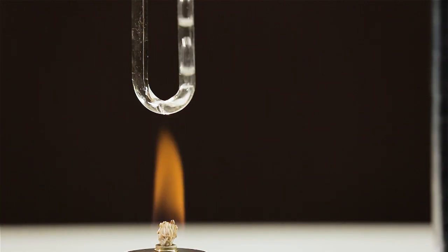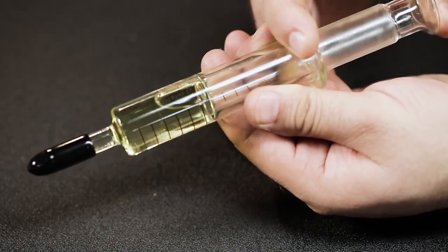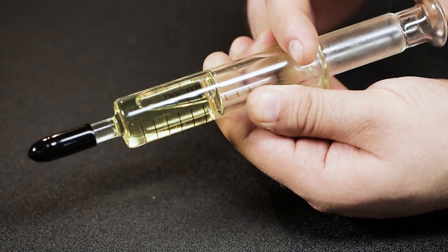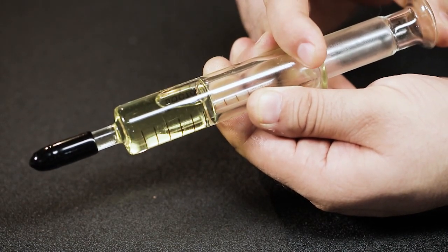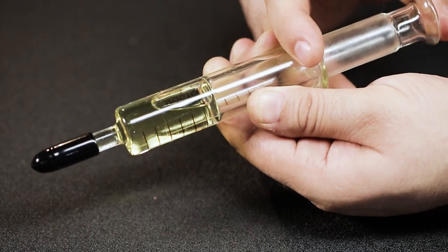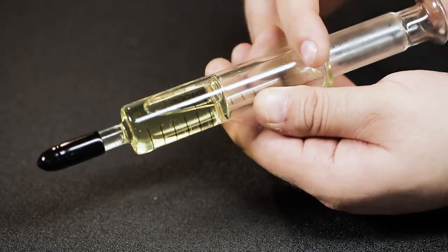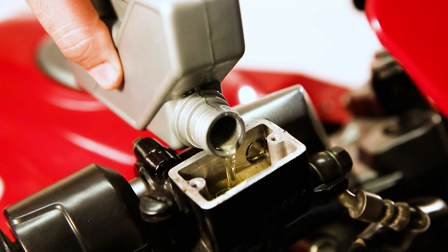When brake fluid boils, a phenomenon called vapor lock occurs. Vapor lock produces bubbles. Because the fluid is pressurized, bubbles in the brake fluid absorb pressure, as shown in this experiment. The result is the brake feeling becomes spongy and the brake effectiveness is abnormal. Brake fluid should be replaced periodically to prevent vapor lock.